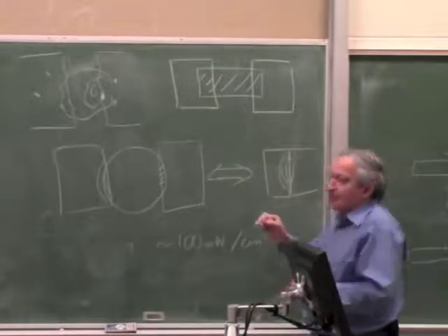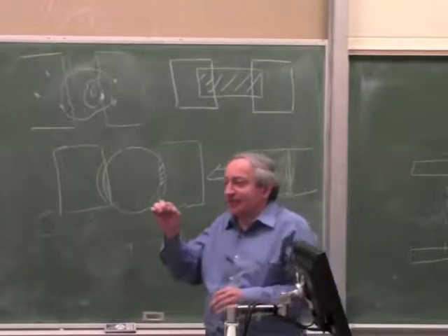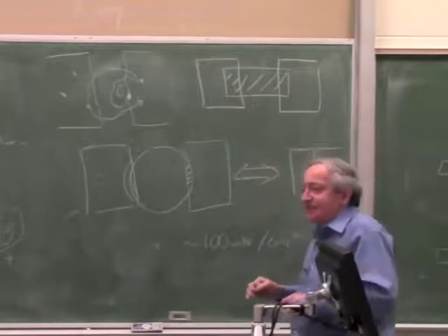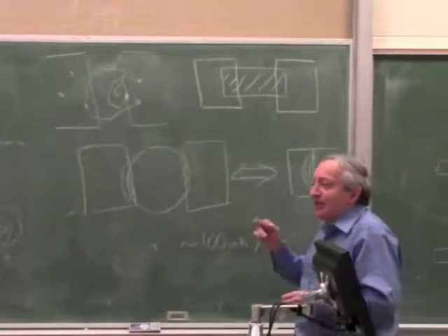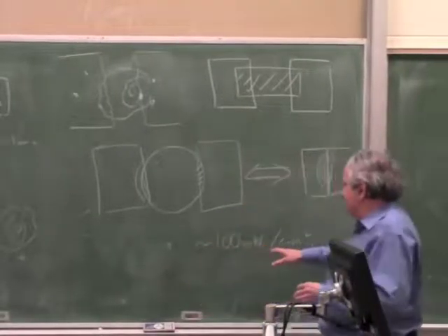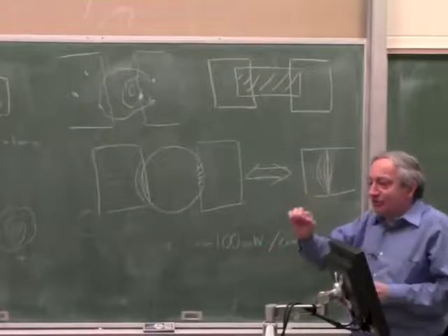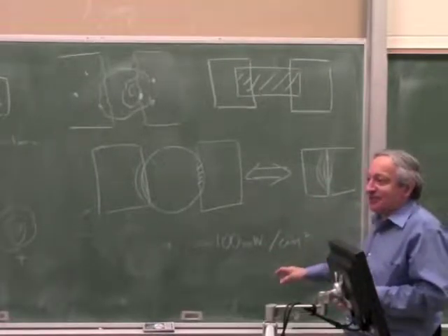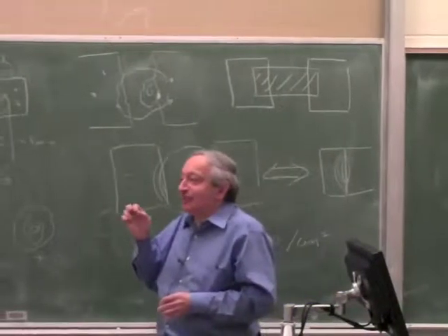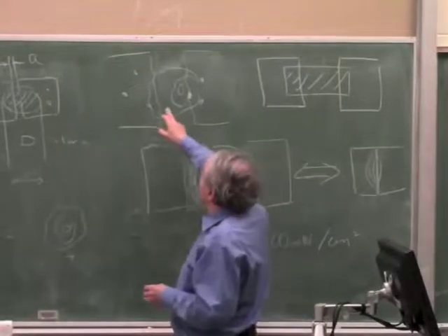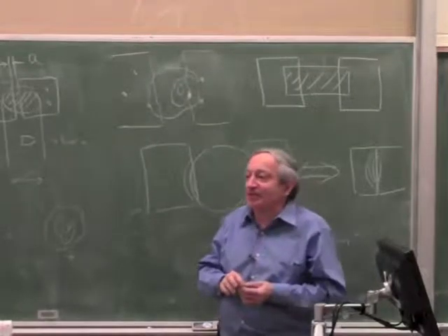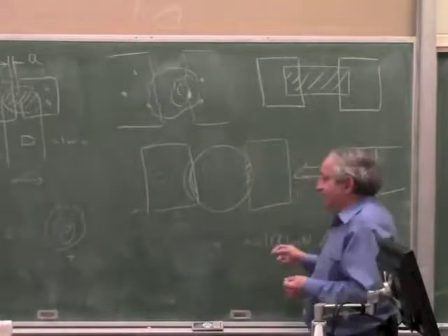Okay? A normal laser pointer has a 3 millimeter spot, which is about 10 square millimeters, and let's say it has 10 milliwatts over 10 square millimeters, so it has 1 milliwatt per square millimeter. So it's about right, 100 milliwatts per square centimeter. But the moment you focus it on a small spot, it doesn't work, it saturates. Okay? Now, especially if you want to measure a 1 micron movement, and you really want to make the gap 1 micron and the spot 1 micron, then the power density will be 10 to the 6 higher than that.